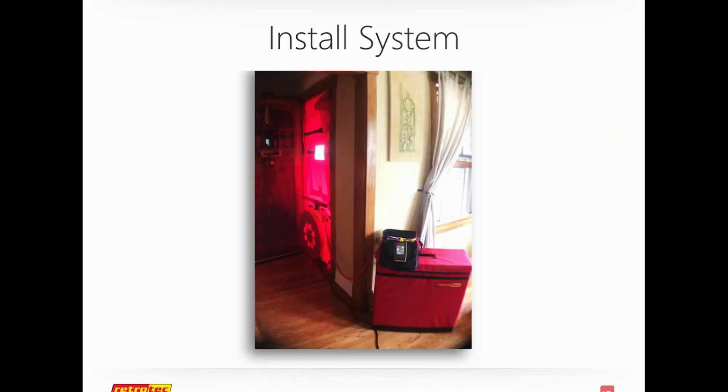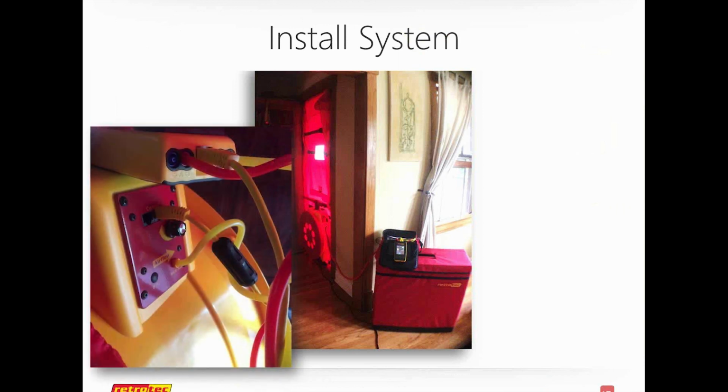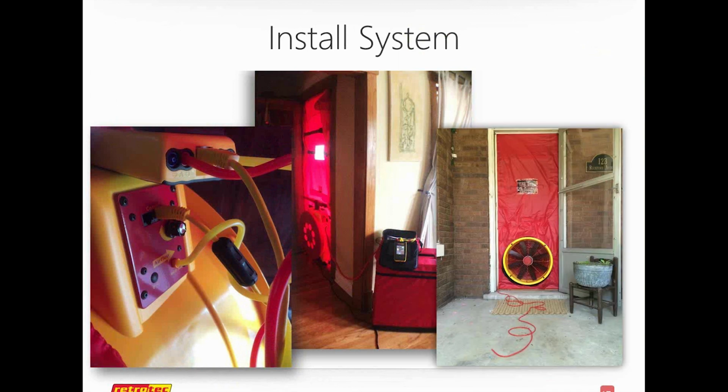So after that, you're just going to install the system. This is what the installed system looks like. Had a question earlier about where's the best place to put the manometer. You'll notice in this picture we have the manometer sitting on its case on top of the blower door case. However, if that's not your favorite place to put it, we do provide you with a place on the panel on the frame to hang it. And I'll show you a picture about that in a second.